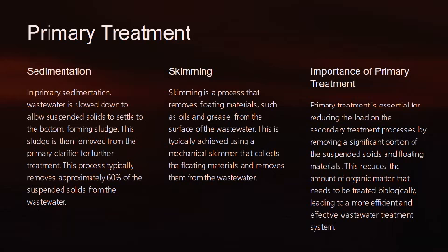But then it's not every single one that will settle to the bottom, because for it to settle to the bottom, it probably has to have a very high density. What about the ones that have low density and can float on the water? That is where skimming comes in. So you fetch out the floating parts, the floating impurities that you don't want. Oil, grease, you try to remove them from the surface of the water.